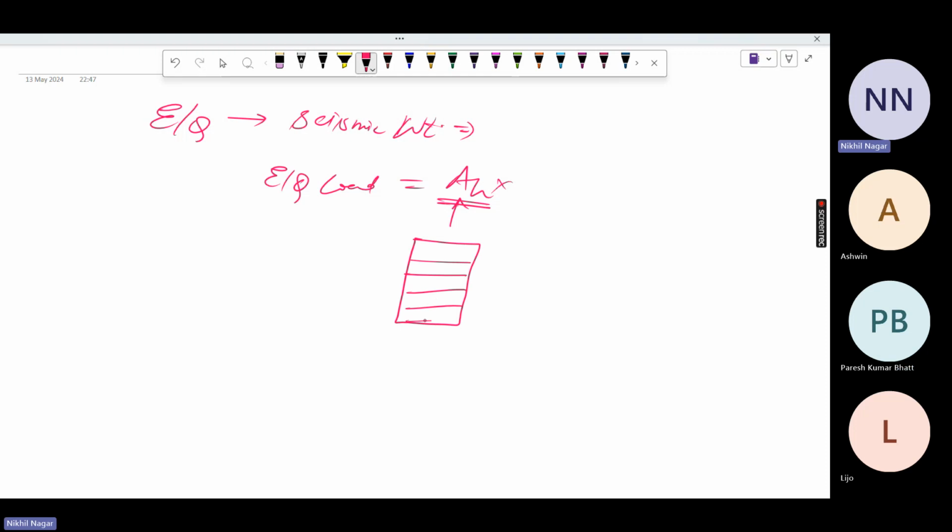That long table, in that you can see we have to assign the response reduction factor, importance factor by giving the values, or you can say type of the building. Okay, residential building, commercial building, OMRF, and zone factor by the city or zone value. Okay, so those will be used in our AH calculation. Now after that, all the things that are covered, that is our seismic weight.